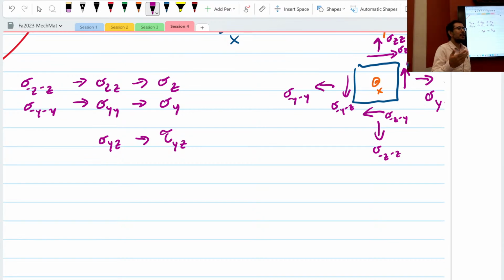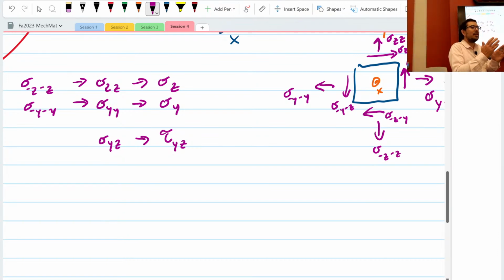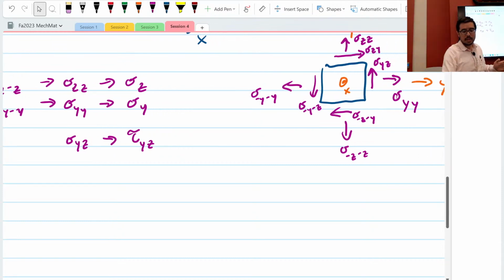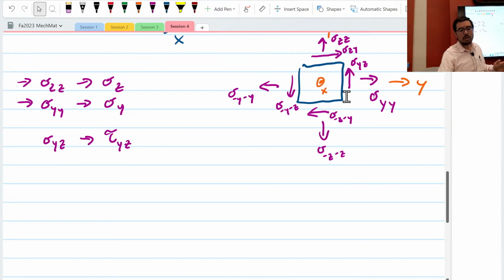So shear is often what you try for. If you go to the machine shop and you're doing sheet metal, you have the big shear. You go in your kitchen, you have scissors. So you often want to try to get things to fail in shear. What is it though? It is a stress that is acting along the face, not normal to it. And you're like, well, duh, that's what you just drew. Yes. Don't be scared of it.